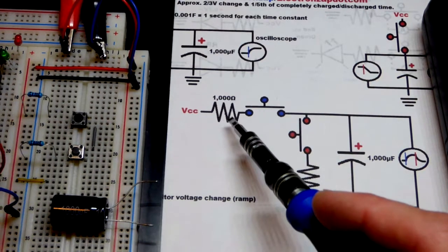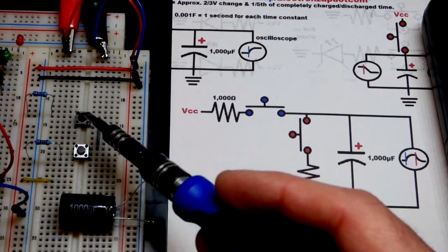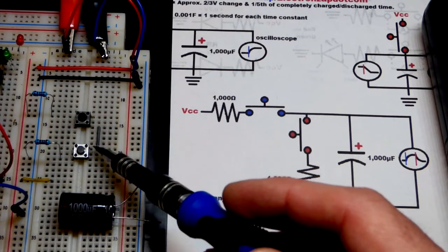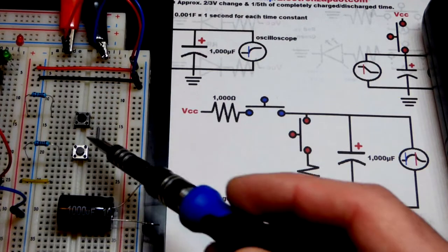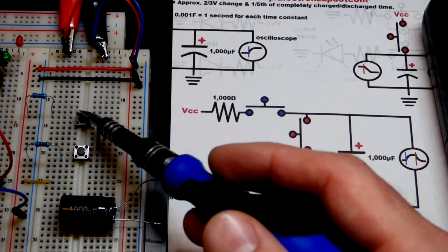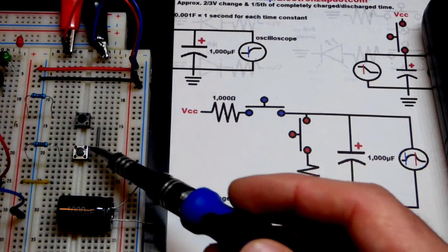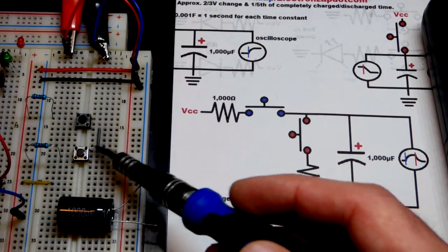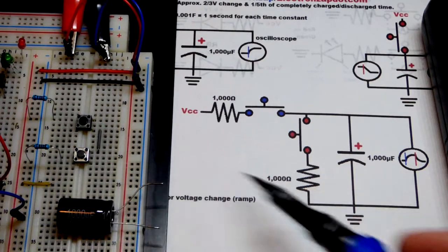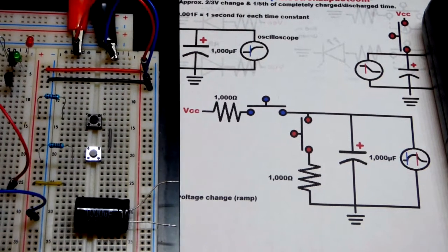And so I have here a 1000 ohm resistor going to the top of that switch, the bottom of that switch connected to the top of that switch. Remember, they're always connected on bottom and always connected on top. They're separated top to bottom. And then the top of this switch is connected to the bottom of that one, and the bottom of this switch is a resistor to the negative rail over there.